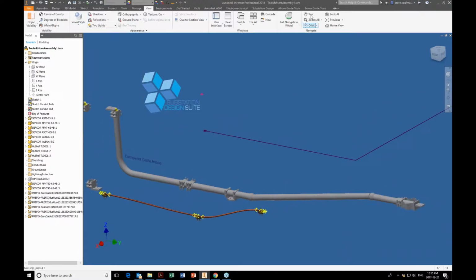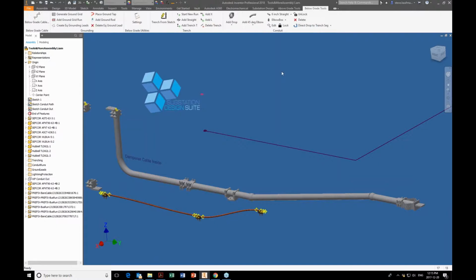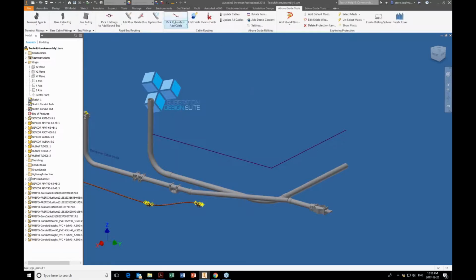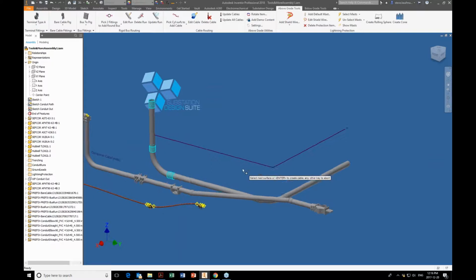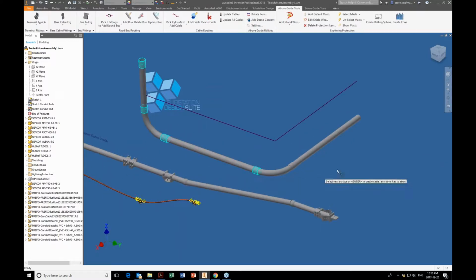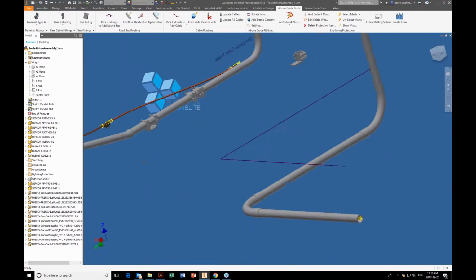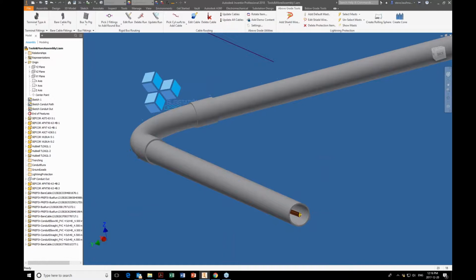So again, if we went into below grade tools, and we're still thinking of that same type of thing, of cylindrical surfaces, I'm going to put my piece of conduit here. And if I want a piece of cable in that conduit, I would be doing the same thing. I'll be picking the surface, cylindrical, cylindrical, cylindrical. And I want to end on this one. And with that, I have the cable on the inside and cable on the inside there.